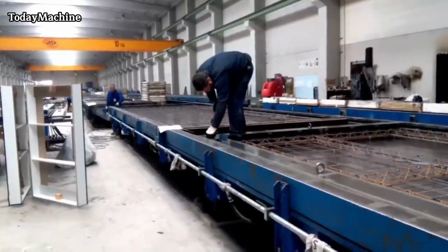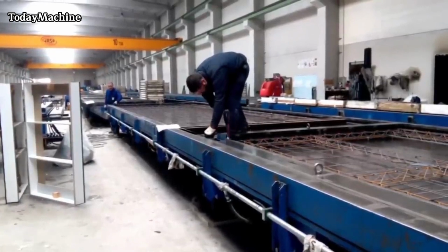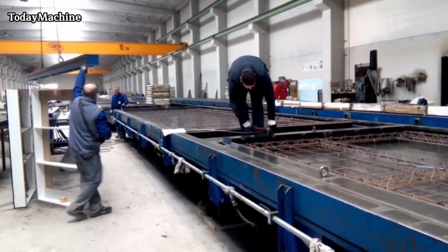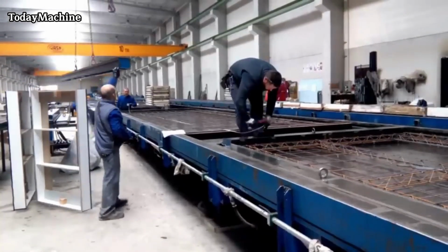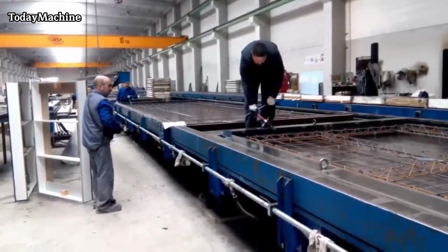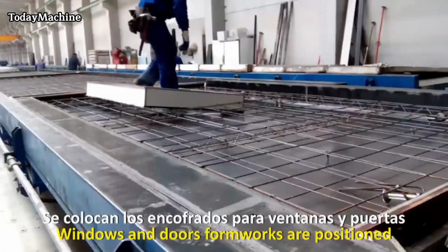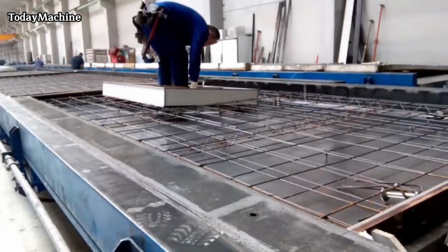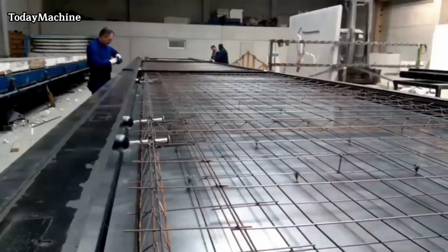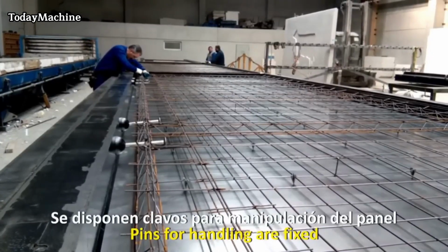After the separators have been placed on the table, it is essential to verify their final positions. This step involves meticulous inspection to confirm that the separators are correctly aligned and spaced according to the design requirements. Accurate positioning is critical because any deviations can result in panels that do not meet the specified dimensions, leading to production errors and rework.